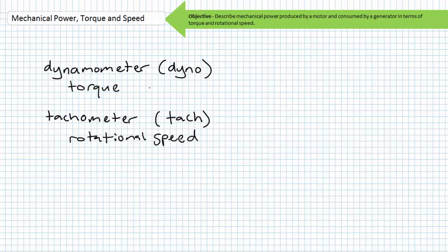A dynamometer measures torque, and a tachometer measures rotational speed. The product of these two, then divided by 9.55, is mechanical power. If you measure the amount of seconds one is delivering or consuming power, and multiply that time by power, you get energy in joules. Sounds familiar? Energy results from 3 easily measured pieces of data: torque, speed, and time.